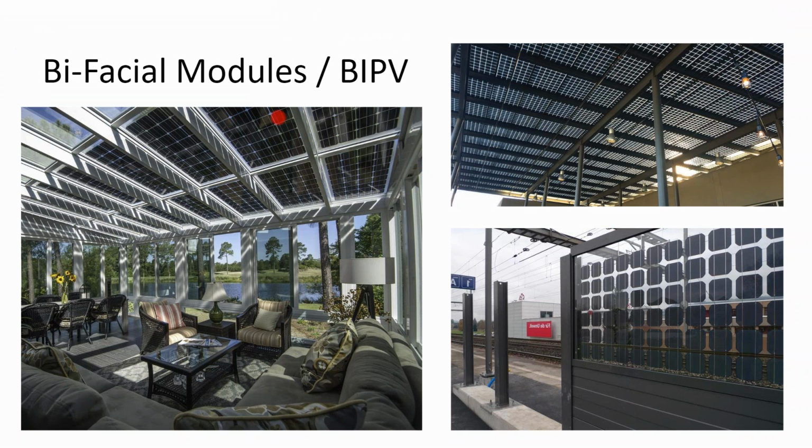And at that point, it gets a little hard to find bifacial panels because most of them are like this, where the cells are really closely spaced together. Whereas I think the ones where the cells are spaced further apart are prettier and more logical, because you want to let the sunlight through. But the further apart you space the cells, the more you're buying a sheet of glass and not a solar panel, and so it becomes even less cost effective.